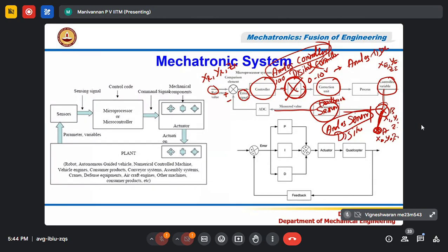If the signal is coming continuously with respect to time, it is an analog signal. Instead of that, a sensor can provide a binary number. Correct? Say it is measuring force, from 0 to 10 Newton. 0 Newton is represented by all 0s, an 8-bit number. And 10 Newton is represented by eight 1s.